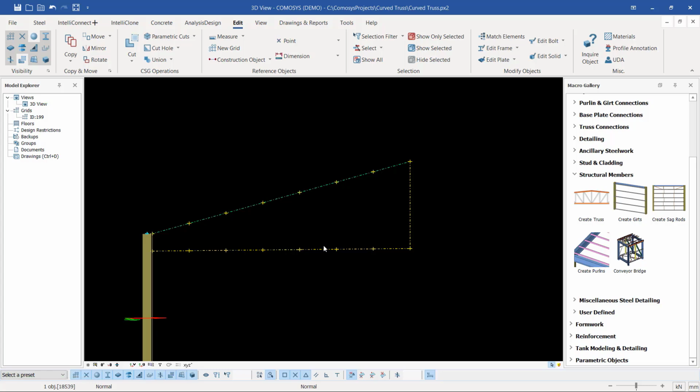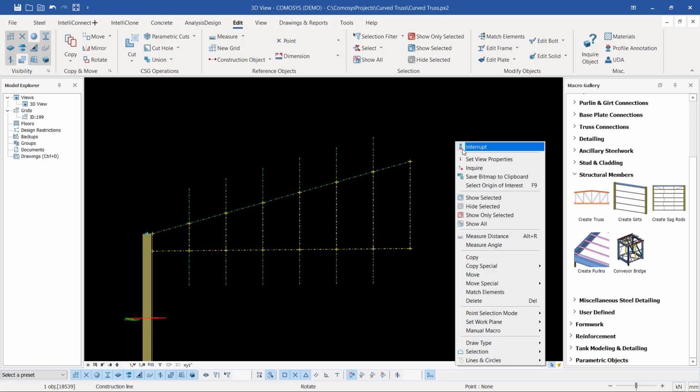So what we are going to do here, we are going to now start placing the lines along these members. So what am I going to do? I'm going back to construction line and pick on the construction line, and I'll place this line there. Place that line there. Just snap. Make sure you snap accurately to make sure it's accurate. Wait for that red snap to appear. So the moment it appears means you are on the right intersection point. So I'll join that line to this line, and I'll join this line to this line. Perfect. So that's how you'll do it.